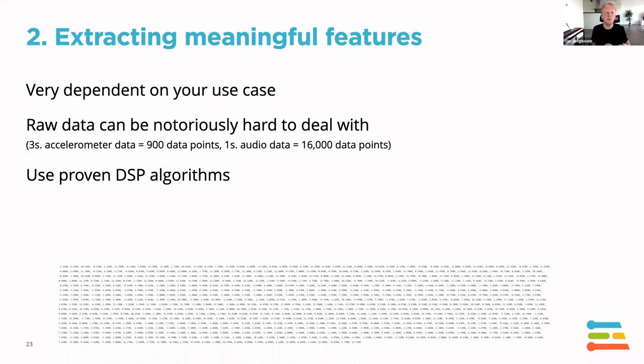So my next step will always be, after you've got the raw data and you already know what features could be meaningful, if I have vibration data, probably running an FFT over my data and then looking at the peaks in the FFT or at the spectral power density. Yes, wonderful, great idea, do that first. So if you have a way of extracting some meaningful features, do that first.